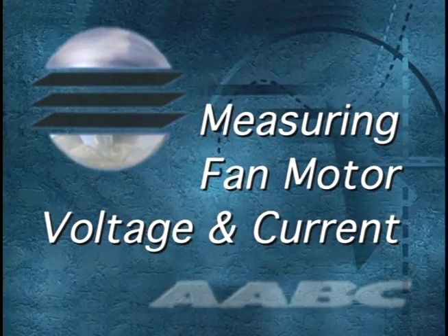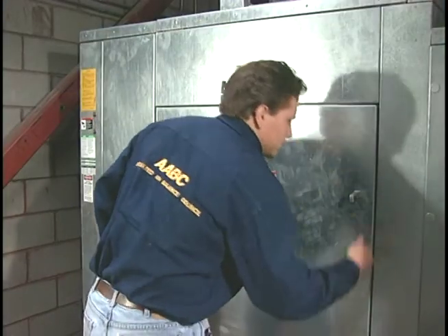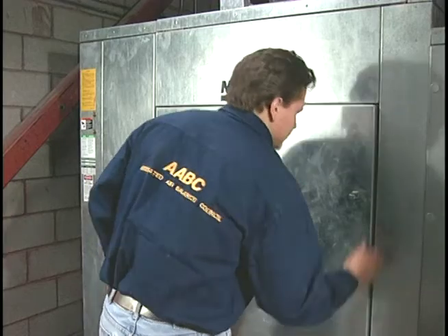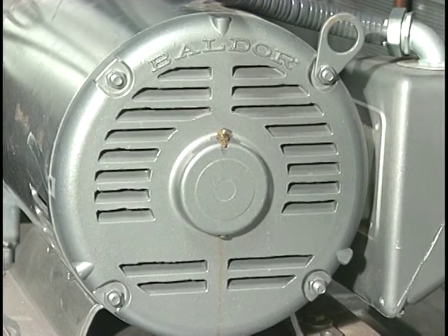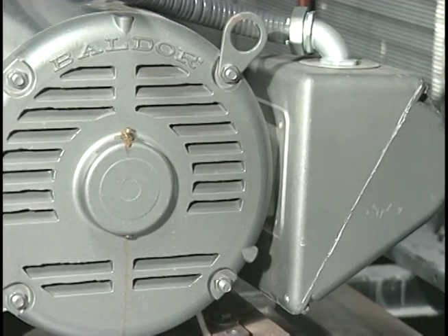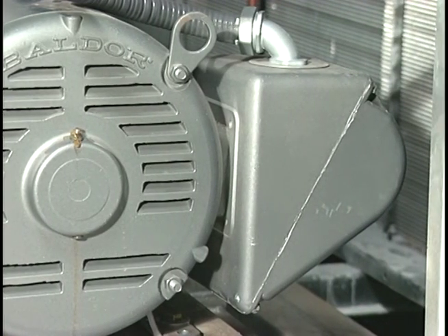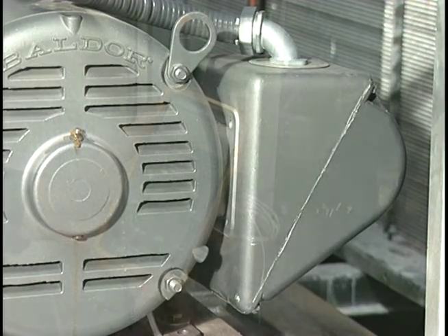Measuring fan motor voltage and current. As a general rule, voltage readings should be taken as close to the motor as conditions permit. Voltage readings are most accurate if taken directly at the motor terminal box, because they reflect voltage losses caused by resistance in the wiring or bad connections.